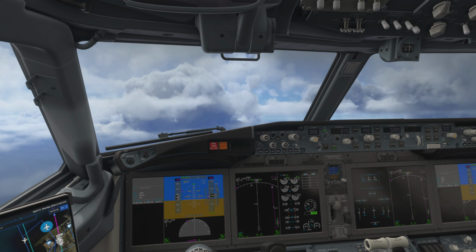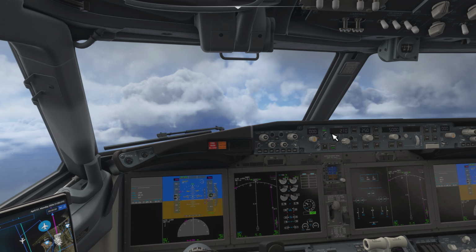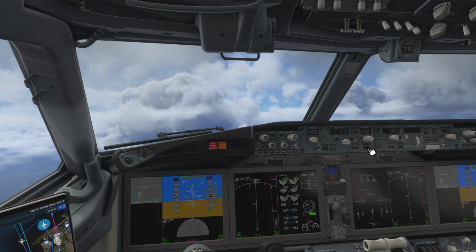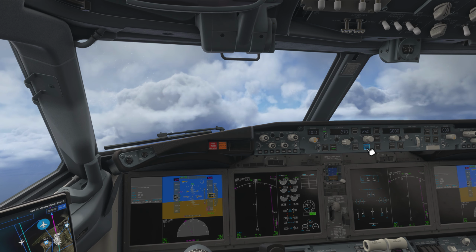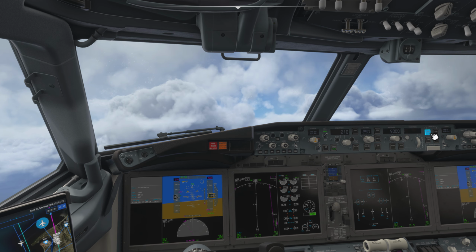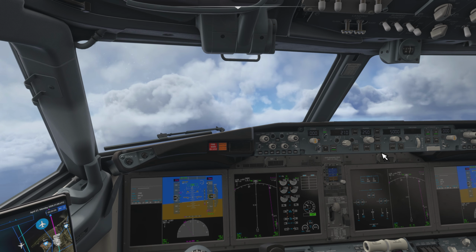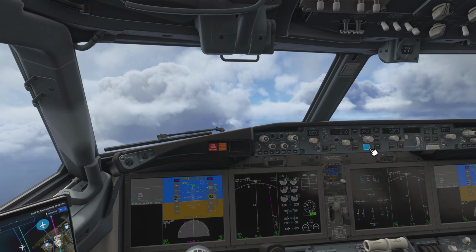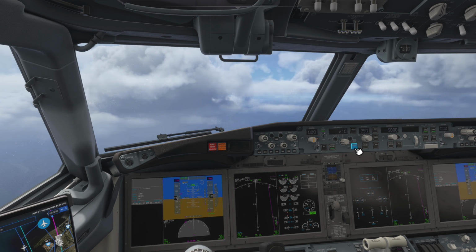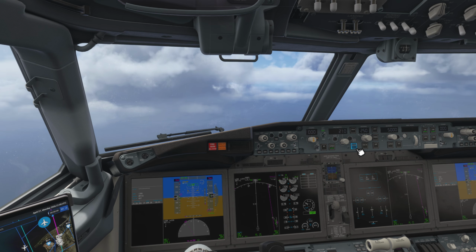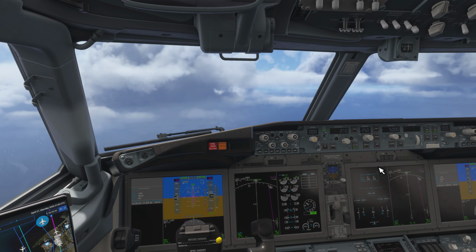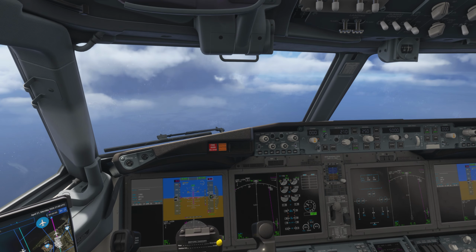And let's get over here. Turn the autopilot system on. When we turn it on, we're going to hit the altitude level change button here. That's just activated. And then, okay. So we got autopilot. That's going to start kicking in.